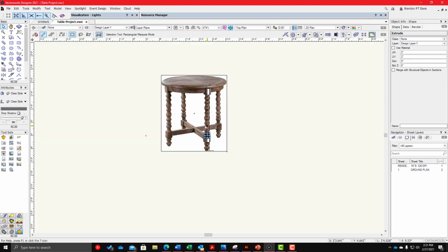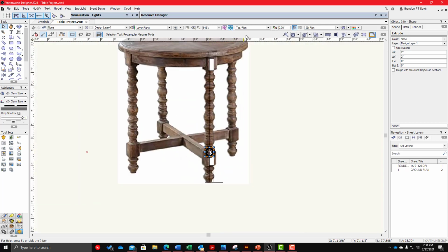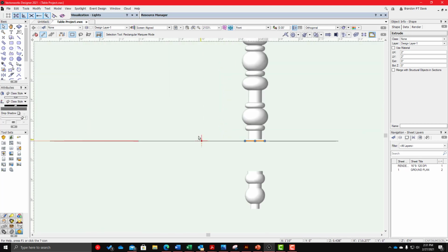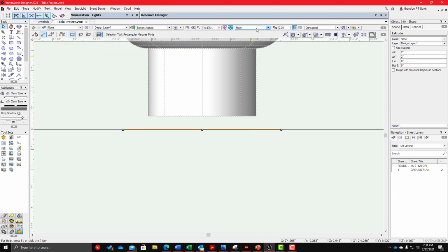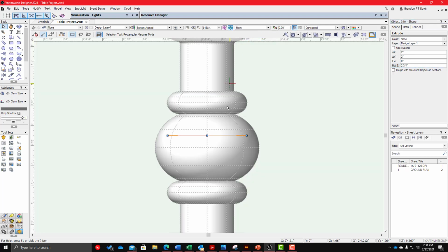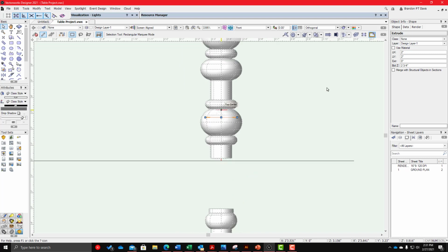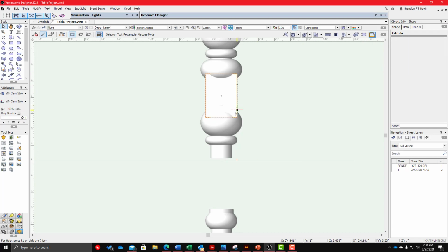Oh no, where'd he go? If I go to the front view, sometimes this happens. So let's see what happened. We're a little bit lost. So our extrusion, I guess I messed that up. Let me figure out why. Oh, I extruded it at 0. So it's extruded, but I didn't put 2.75. I have a new keyboard. It's being a little bit troublesome. There we go. So now if I go to front view, oh, that's the bottom Z. So 2.75. There. Now it has thickness.